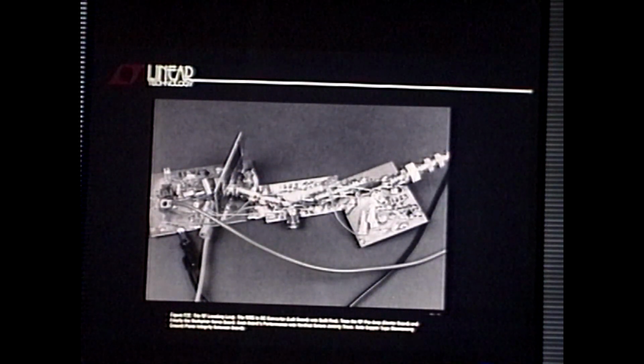So you say, fine, that function of this thing works. The RF preamp to drive this thing. Okay, and finally the multiplier here to close the AGC loop. Then you tack all the copper-clad boards together to maintain low impedance in the grounding network, and hopefully the whole thing's going to work. So I checked out each one of the three functions first and tacked them all together.